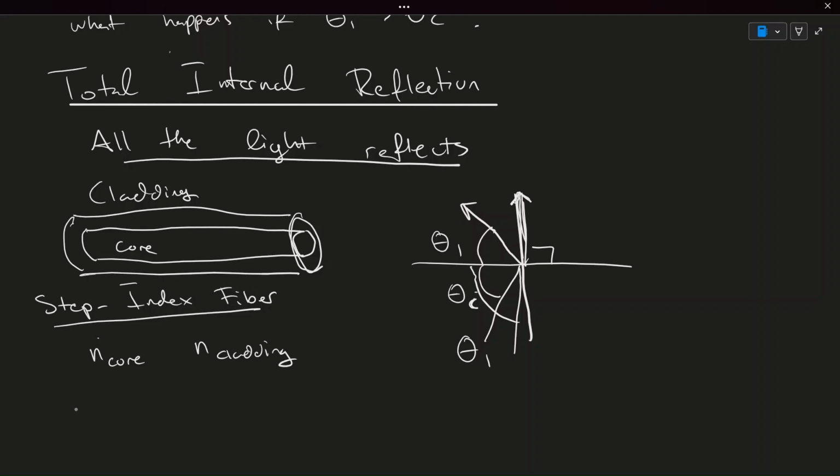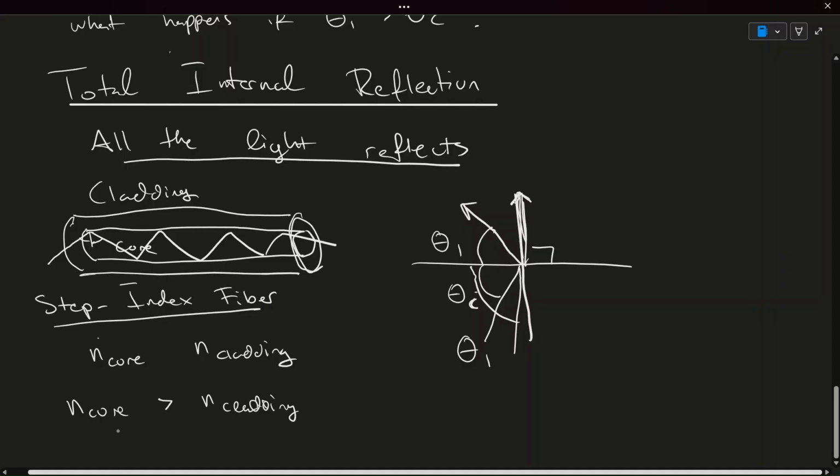There's a way to design it, which I won't go into detail about right now but in future videos, where you make the index of refraction of the core slightly larger than the index of refraction of the cladding. In a way so that if you shoot light in at an angle more than the critical angle at the very beginning, then it'll completely reflect all the way through, because it'll reflect with the same angle that it's shot in, so it'll have total internal reflection again, and the same angle again, and so forth, all the way to the output. By manipulating the materials you use, the core and cladding are made with specific materials of glass that allow total internal reflection, abbreviated TIR, to happen at every single boundary, because it's just doing the same thing over and over again.